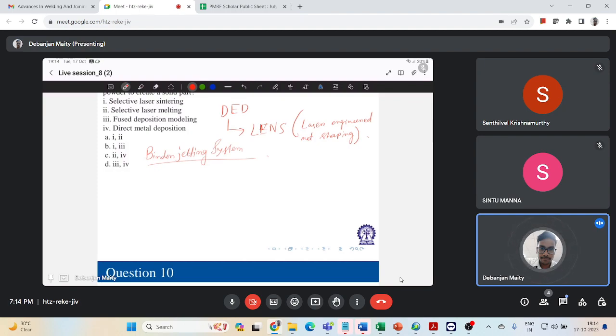And after deposition, depending on the machine and binder chemistry, the binder can be either partially cured between layers, or it is required to completely dry out, giving sufficient strength to be removed from the powder bed system and then cured for some more hours.